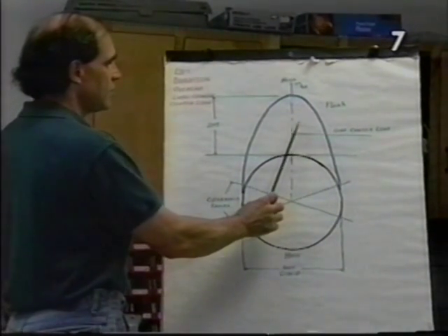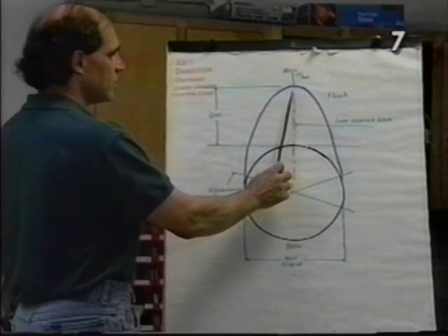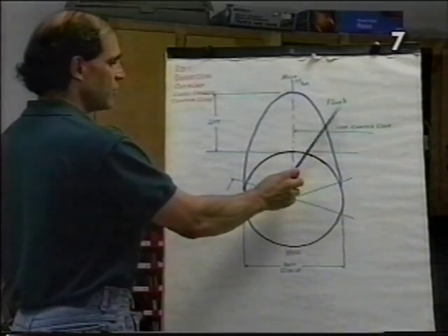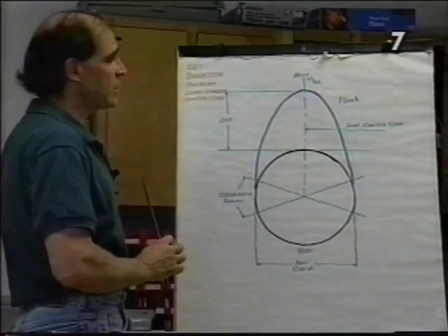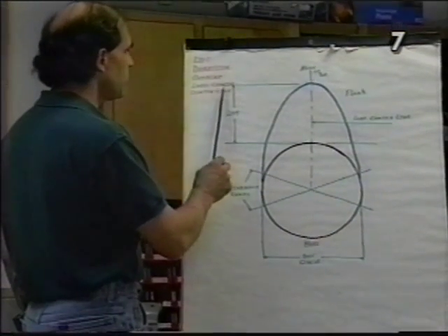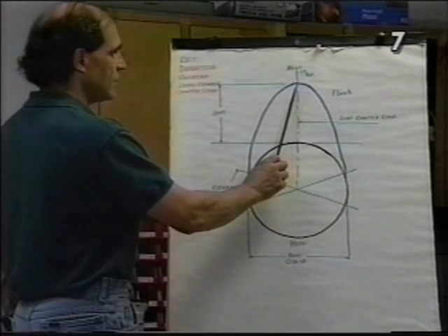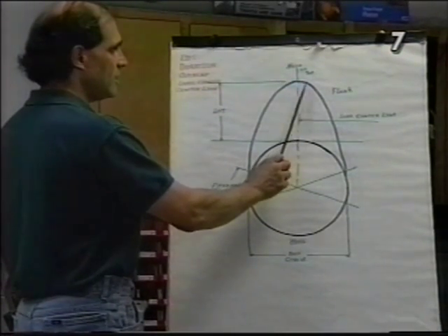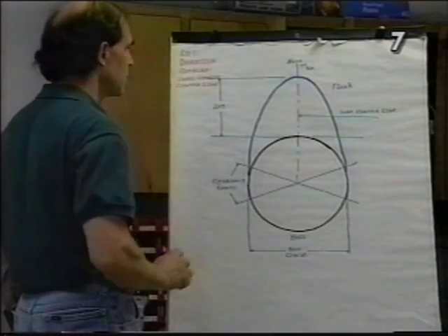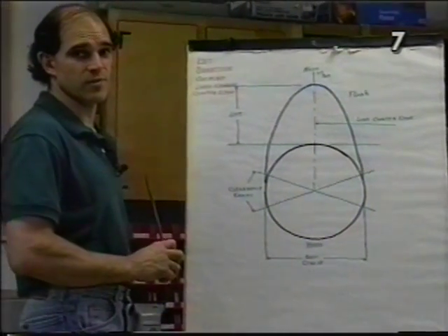Overlap is a period of time that both the intake and an exhaust valve will be off the seat simultaneously. Lobe center is the measure of degrees between the center line of the intake lobe and an exhaust lobe. We will discuss them further in a few minutes.